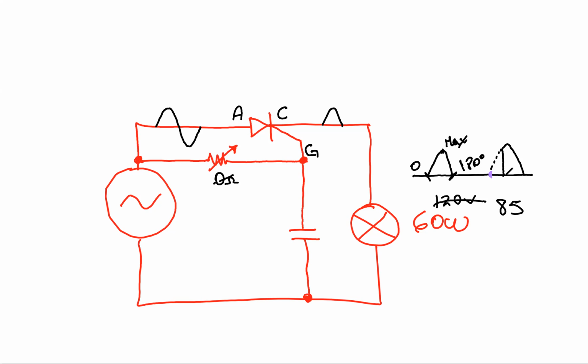So you can see here, in this instant, that when I used to have 120 volts, my SCR was turning on right at this point here, okay? However, when I increase the resistance and I tell the SCR to start the firing sequence later on in the cycle, then I can shut off part of my cycle, thus reducing my average output voltage to a lower voltage.